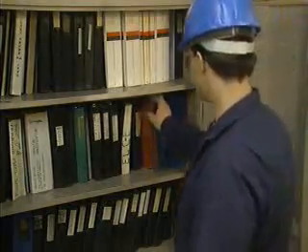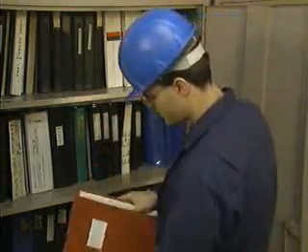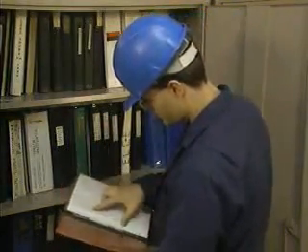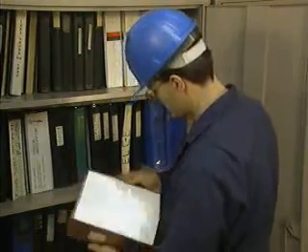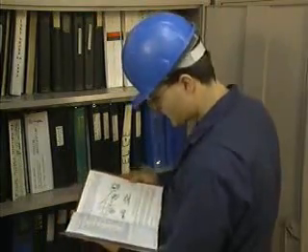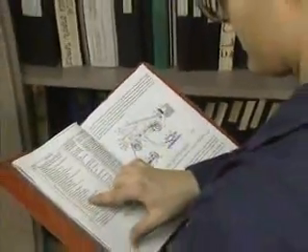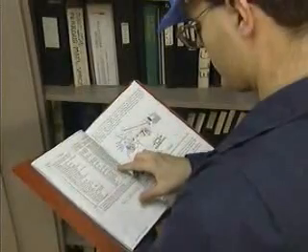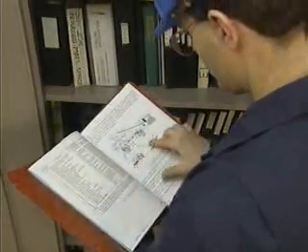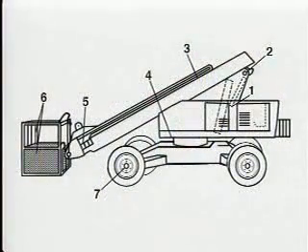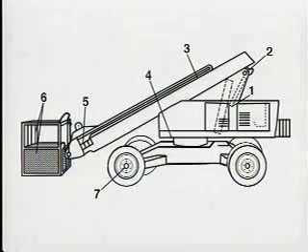To make sure that they use the correct lubricant for a specific piece of equipment, workers usually refer to the lubrication chart that's supplied by the equipment manufacturer. The lubrication chart applies only to that particular piece of equipment, and it should not be used as a lubrication guide for any other equipment. Often, each lube point or equipment part that requires lubrication, as indicated on the lubrication chart, is shown and numbered on an illustration that accompanies the chart.